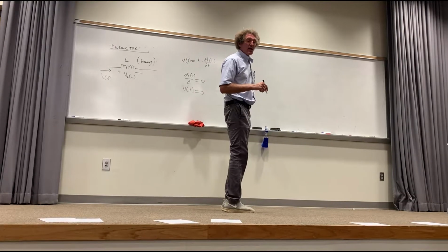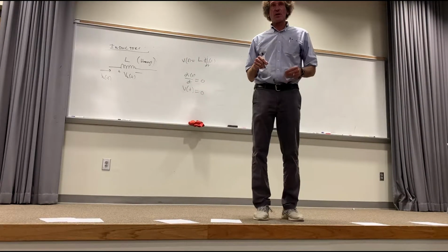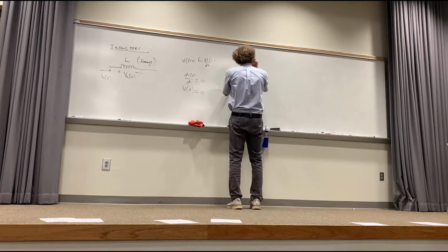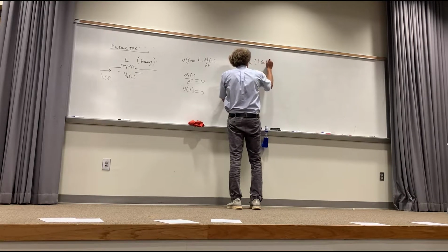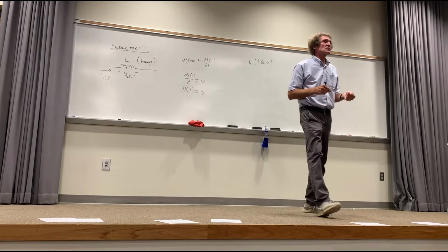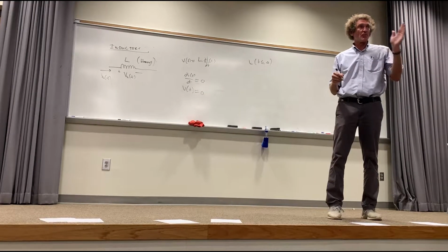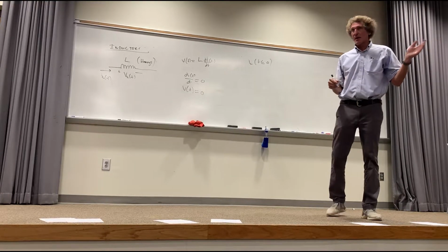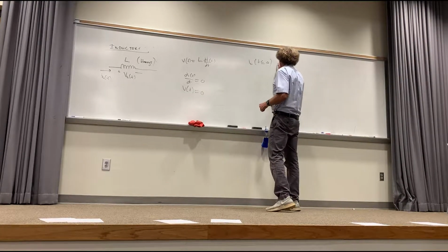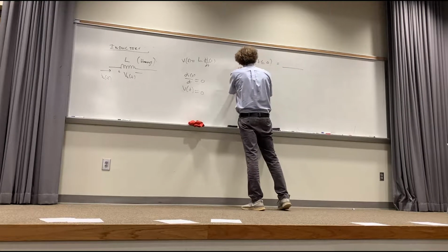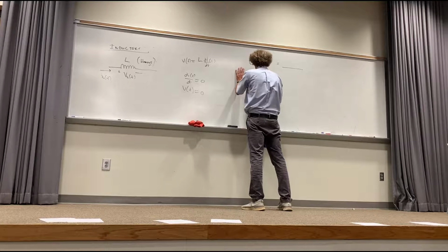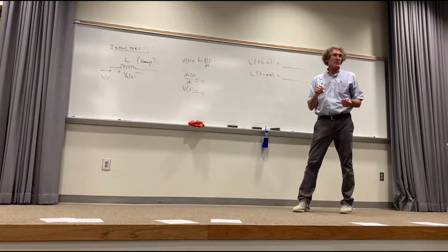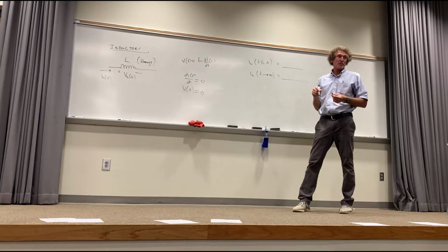Before, when we had a capacitor, we got the voltage across the capacitor, right? With an inductor, it's the exact opposite. What we do is find the current in the inductor for t less than or equal to 0, or really where the transition begins. If something switched at 1 second, you would go from t less than 1 second to t greater than 1 second. Follow me? Now, we find this value. Then we find the value of the current through the inductor as t goes to infinity. Very similar to before, when it was just voltage at those 2 points, right?